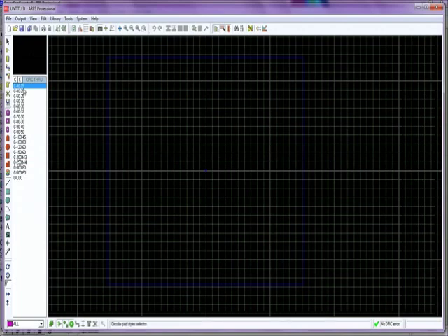This is actually the outer diameter is 40 mils, that is 1/1000th of an inch, and this is 15 mils. Where there is an M, this is millimeters, so this is 0.2 inch and 3 millimeters the drill hole.